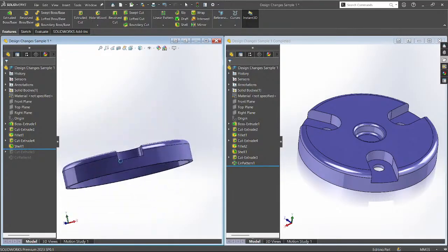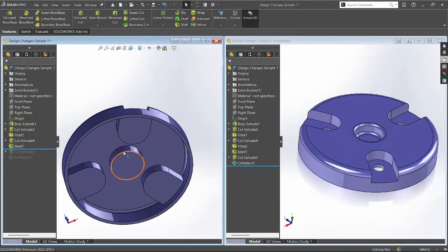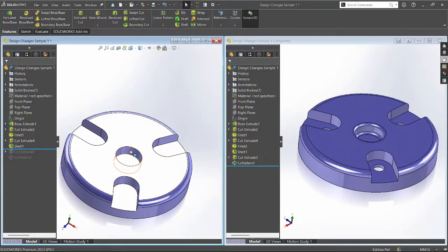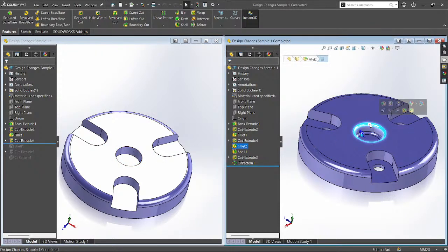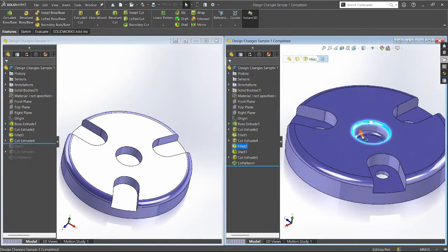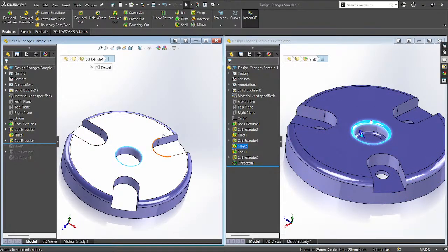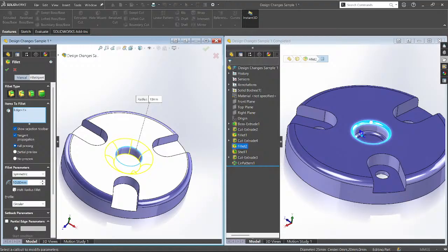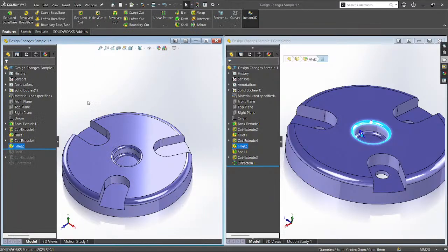Now the thing is, if I create a shell now, it will capture the corners, right? So now what I can do is I can apply the fillet here directly. What would be the fillet? If I just select here, it shows me the fillet value. It is exactly radius 2. I can do the same. I can just select this one and click on fillet, apply the fillet radius 2, and then select the bottom edge. Now click on the green check.